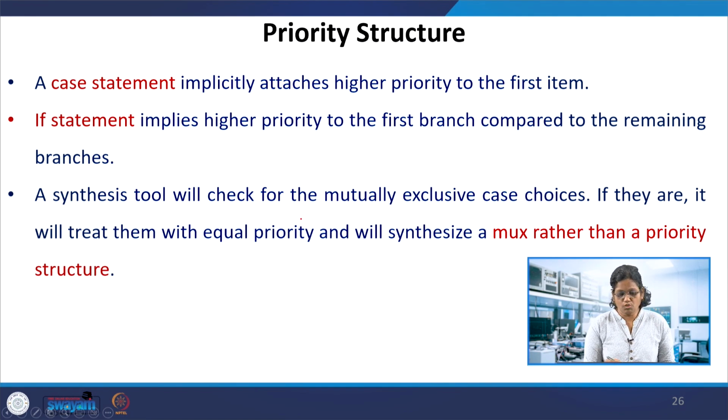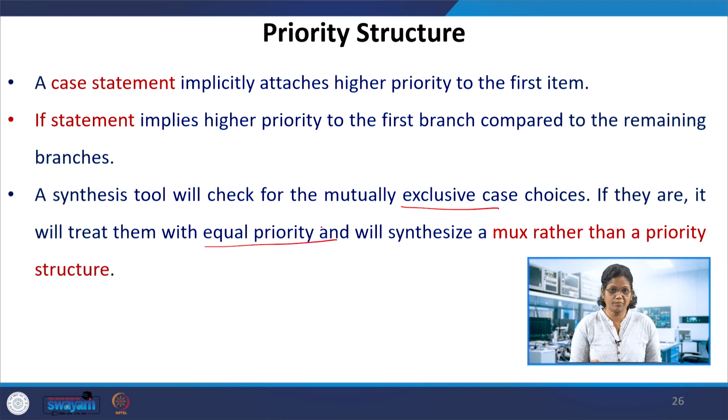The synthesis tool will check the mutually exclusive case choices, and if they are there, that is, the case items are all listed, then it treats all of them with equal priority. So in the case structure, instead of having a priority structure, a mux structure is synthesized.